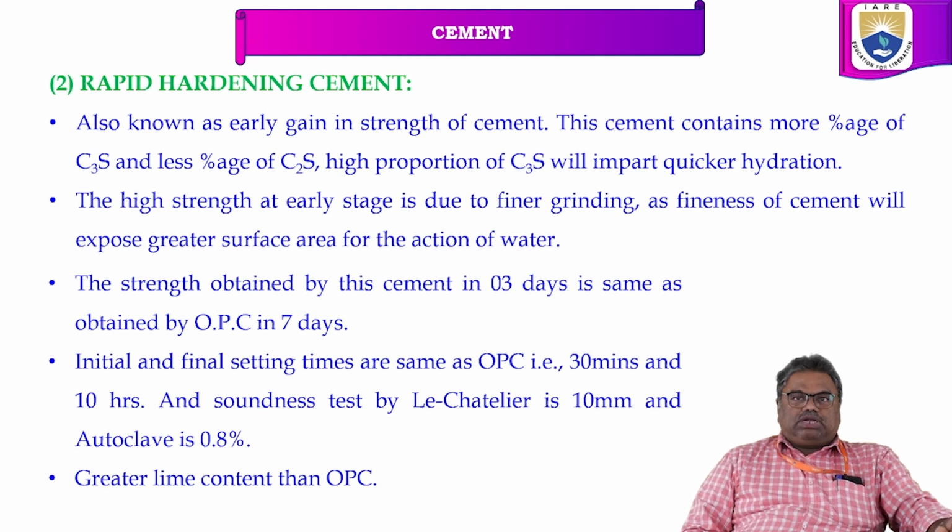The high strength at early stage is due to fine grinding, so that the hydration process will be quicker. The fineness of the cement exposes a greater surface area for the action of the water. So the surface area is more, and if it is finely ground, the hydration process will be quicker.